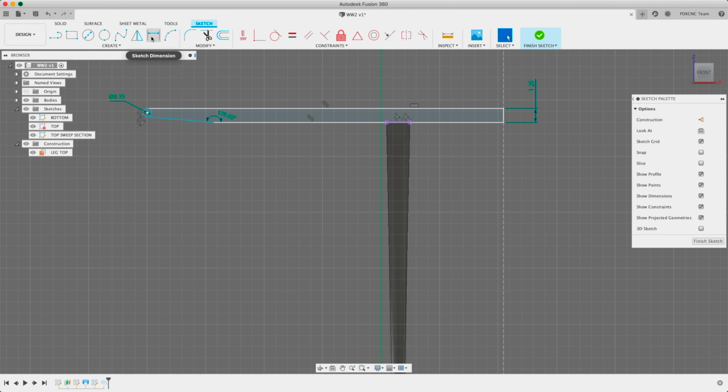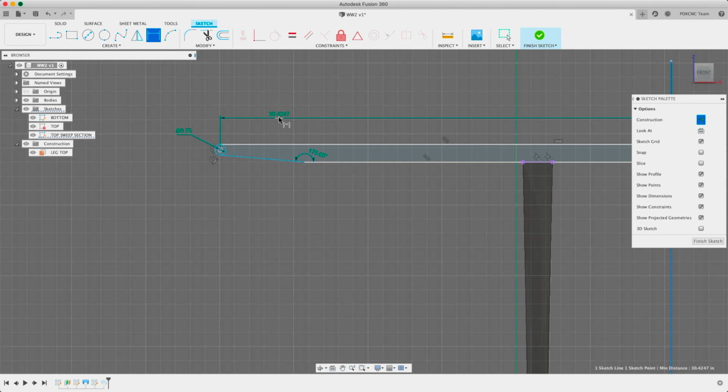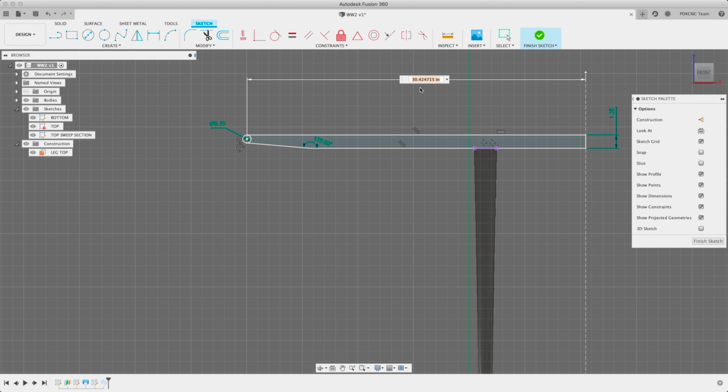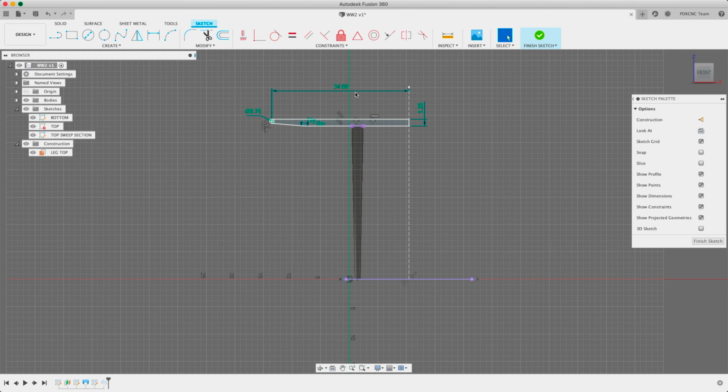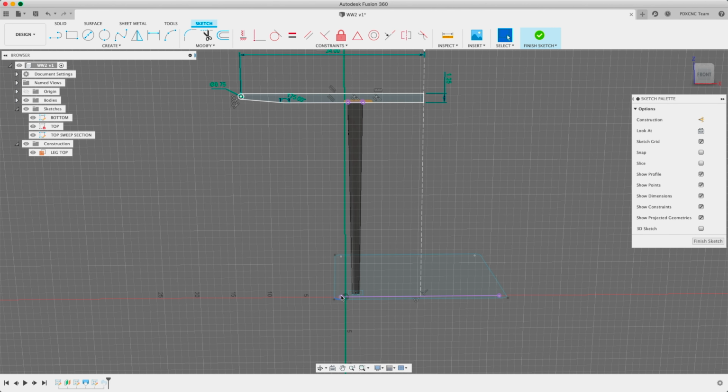So now let's try to dimension our tabletop. A line in the center, out to this guy. A line in the center to our circle. If we drag it up here, now we have a proper dimension, there we go. So that's good. Our parameter isn't quite what I want. That's just dividing the bottom there. So if we said top width divided by 2, that would work.